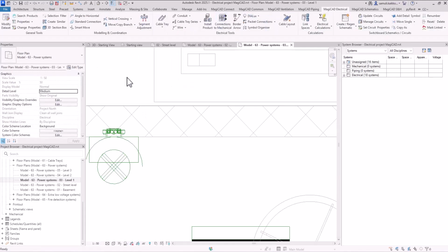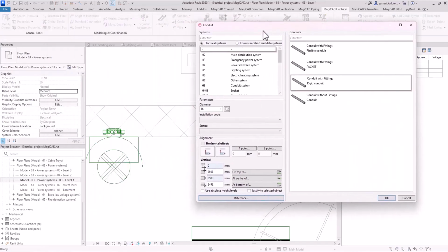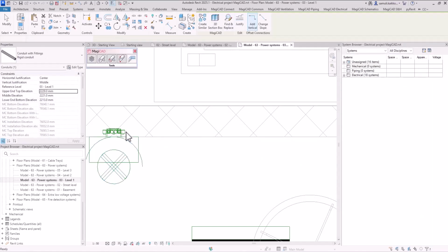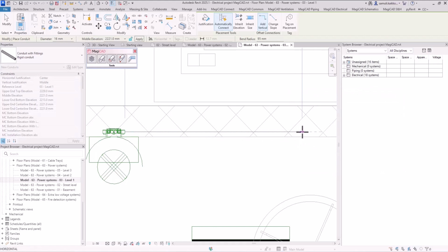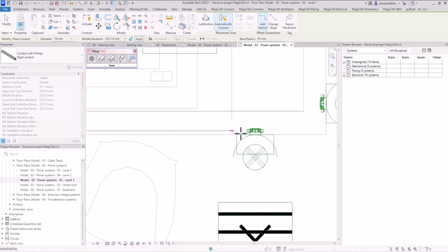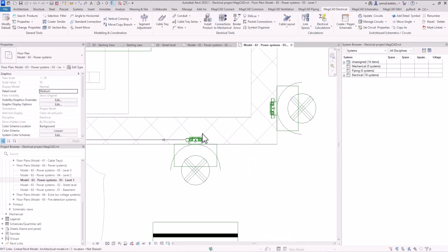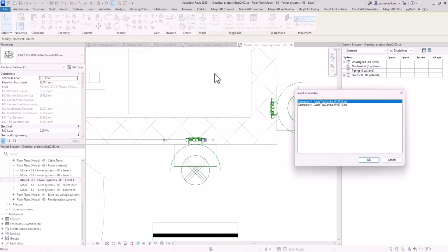Backboxes contain connections for conduits, so you can design a route for cables and use conduits as placeholders for voids needed for concrete elements. By providing a full design, you can ensure the model fulfills all BIM requirements.